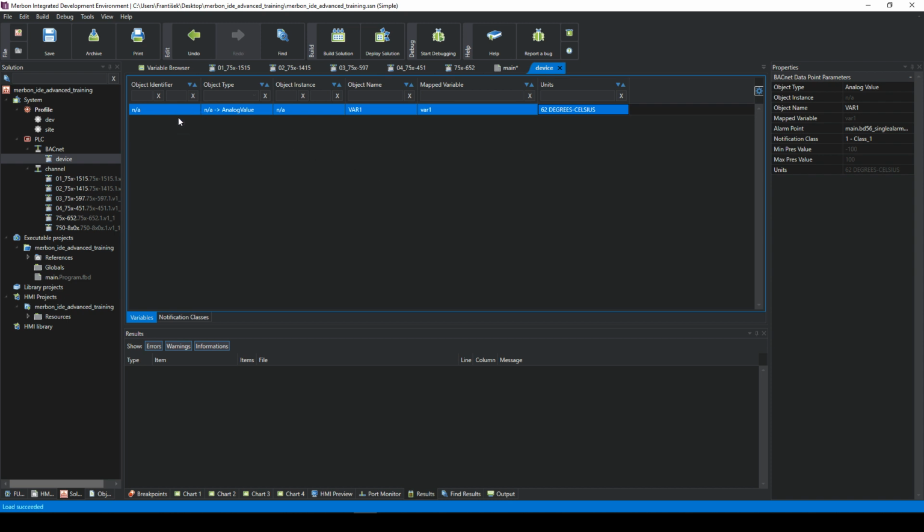The important thing about this identifier is that it's not editable. It will be created automatically. So that's a change also from Modbus. It's a difference. When you're using Modbus, there are registers which have their own numbers. If you use BACnet, the identifiers are created by themselves. You cannot change them. They are created automatically.